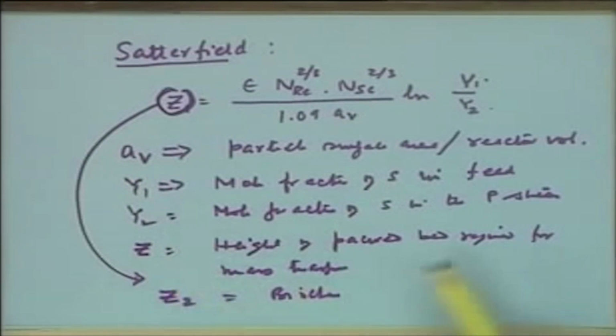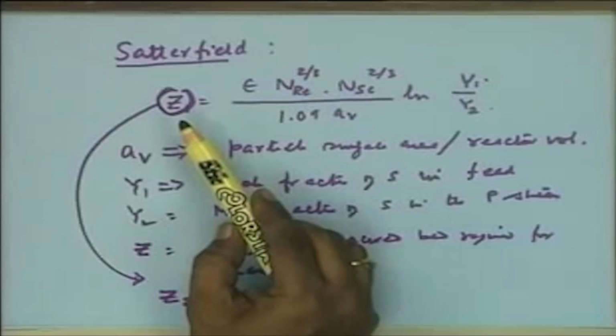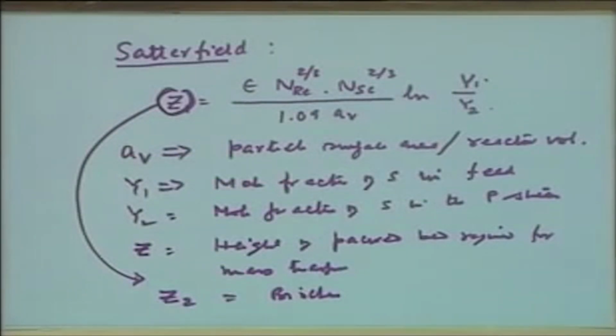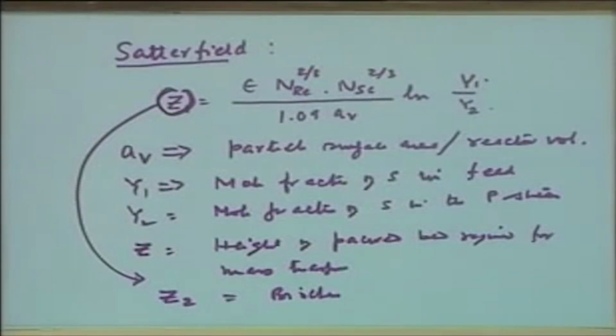You see, normally the substrate is getting transported from bulk to the surface, and at the surface the reaction is taking place. If no reaction were taking place, then along the length of the reactor at Z, the substrate concentration would reach Sb, the same as in bulk. It will take some time. Whereas if the biochemical reaction is also taking place at the surface, then the length required will be given by Z2 at substrate concentration Ss. Now, whichever of the two is larger is required to be considered.